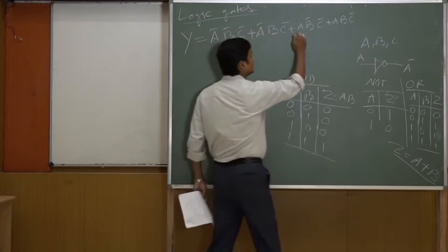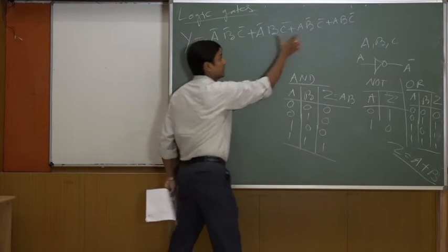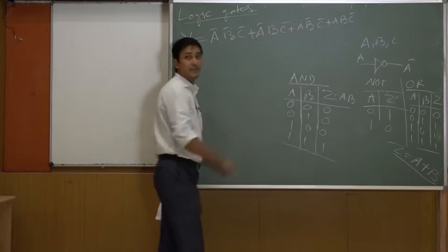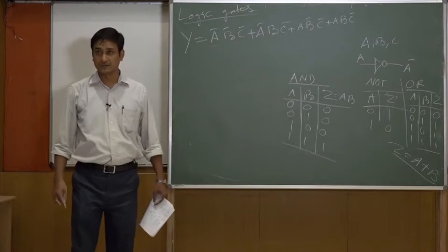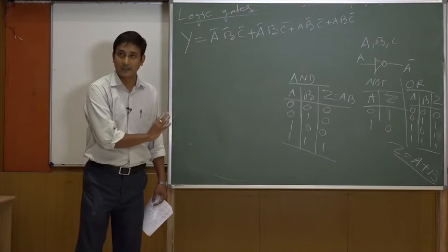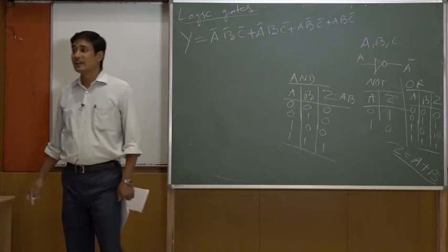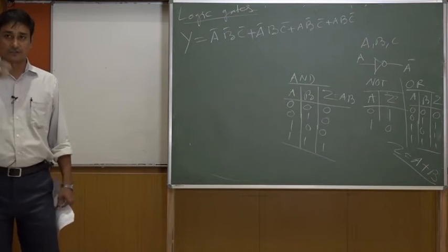Again, if I consider these 2 like that and OR together, then you will get some expression for these 2 and some for these 2, then again you have made an OR operation. So, from 2 input to 3 input we have gone. Okay. Let us implement this circuit directly in terms of logic gates, AND, OR and NOT, please.